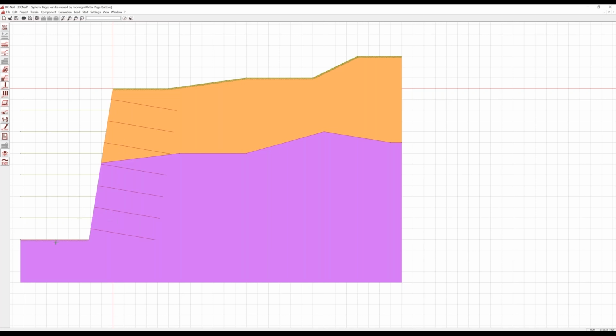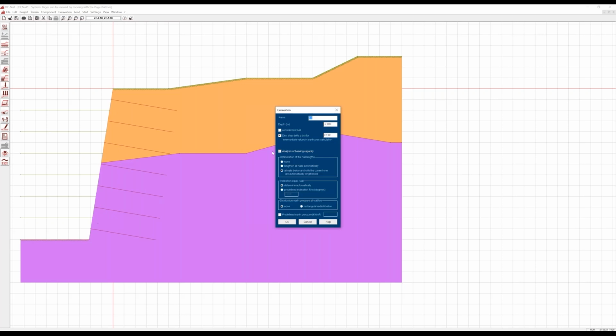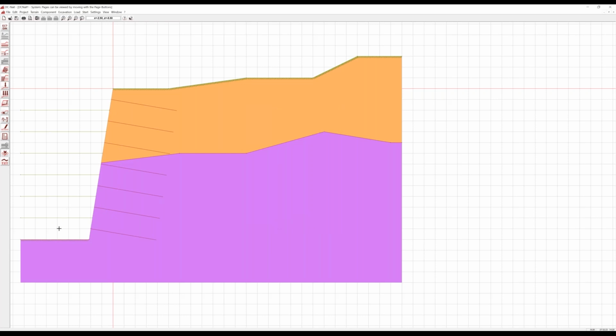And in each excavation stage, we have switched off to consider the last nail. So we first have to excavate here and can then enter this nail layer. So finally, we need one excavation stage where the last nail is acting. So for example, I can copy here with copy and paste. I copy this excavation stage.